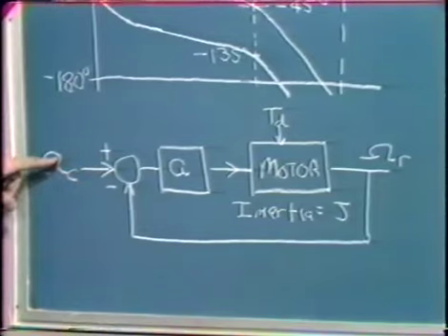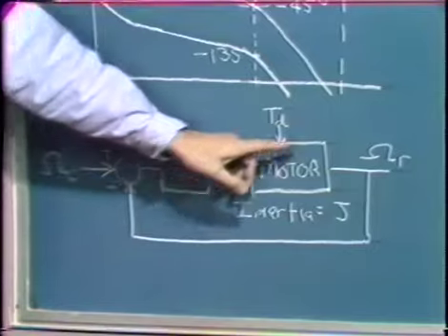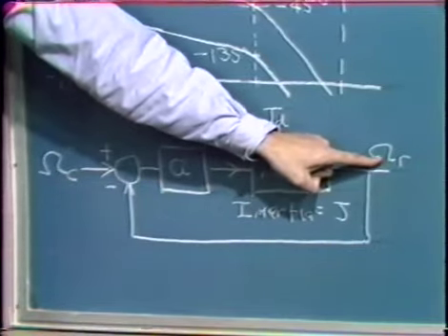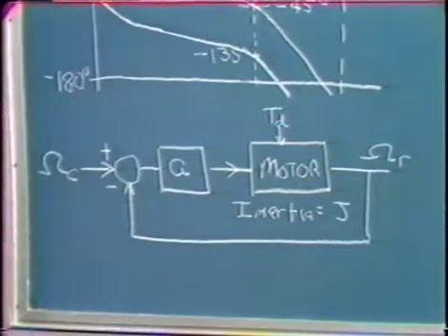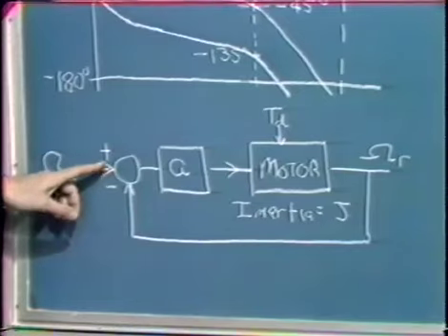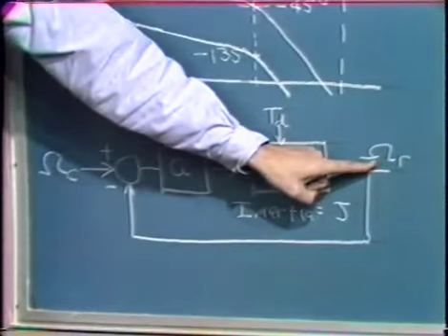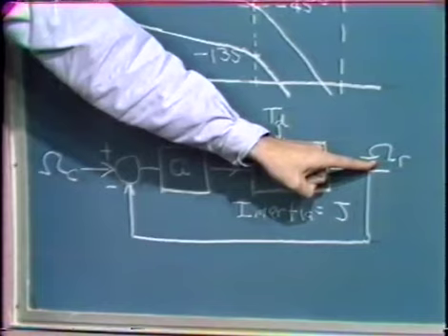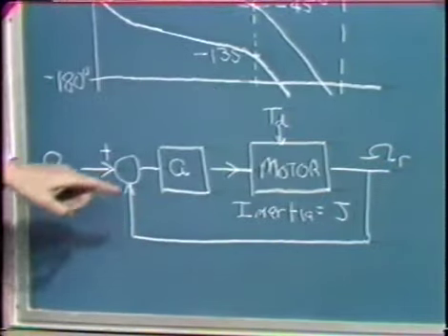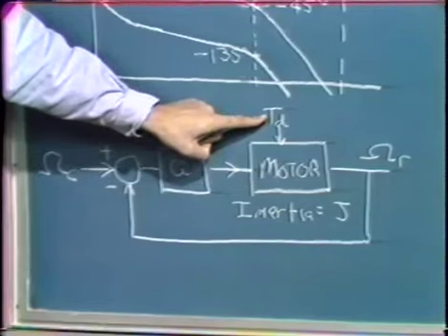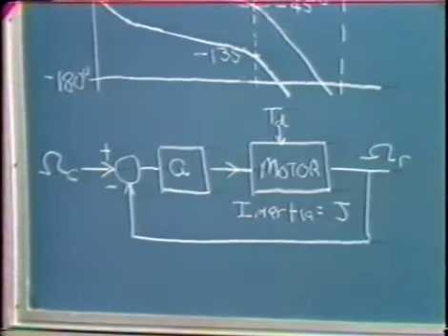So we put in a command, and our hope is that eventually the system reaches a speed that's about equal to that command in the system I've shown. Notice that we have unity feedback in this system. And from then on, the intent of the feedback system is to keep the output velocity fixed. And the disturbances that we'll consider are torque disturbances that are applied to the mechanical system.